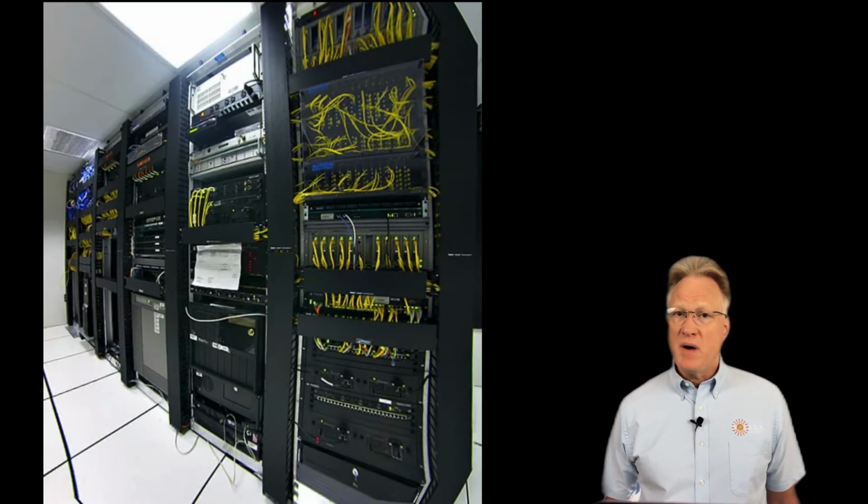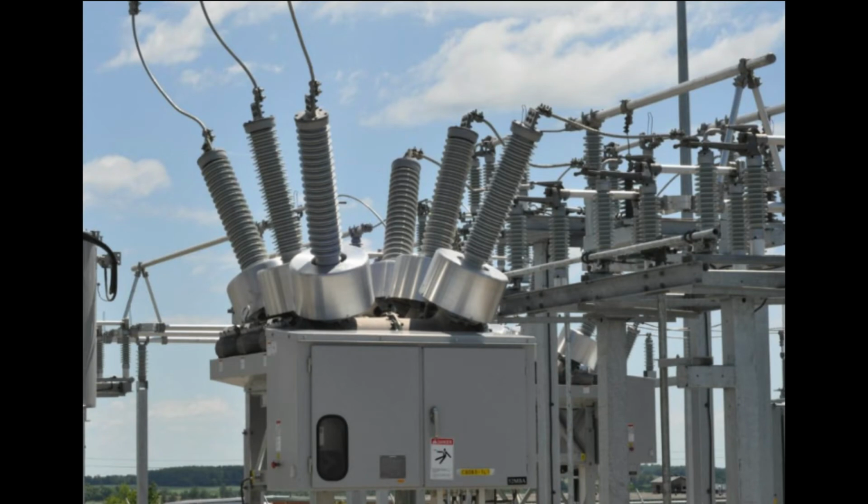The equipment being powered will govern the allowable operating voltage range of the system. Do you need a single voltage system or dual? For example, if the communication gear needs 48 volts and a 125 volt bus is available, should the communications equipment be powered by its own battery and charger system, or with a DC to DC converter fed from the 125 volt DC system?